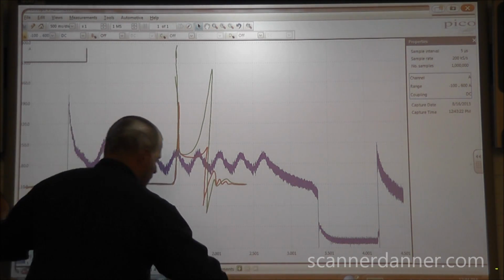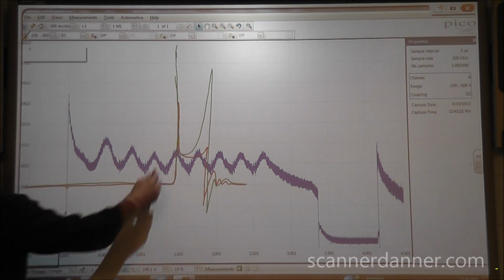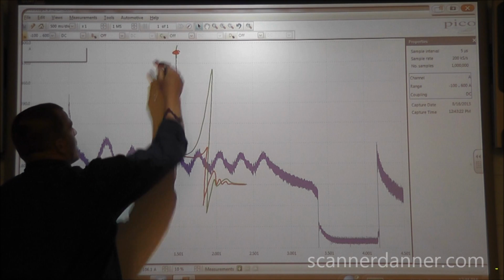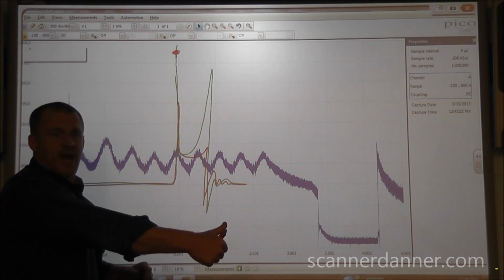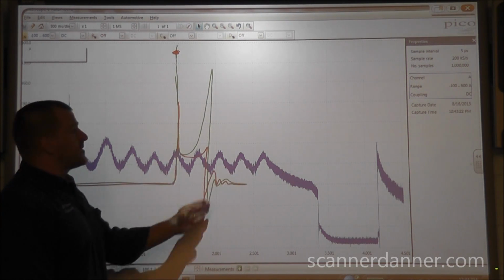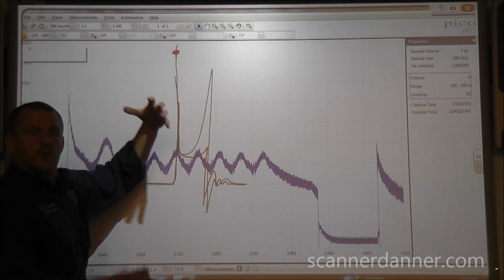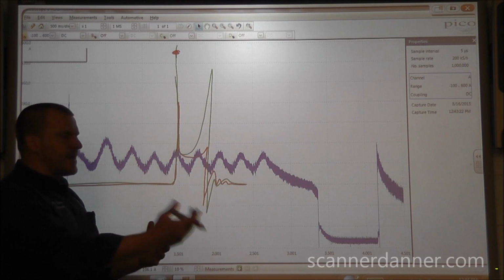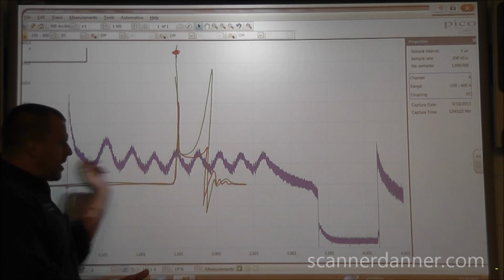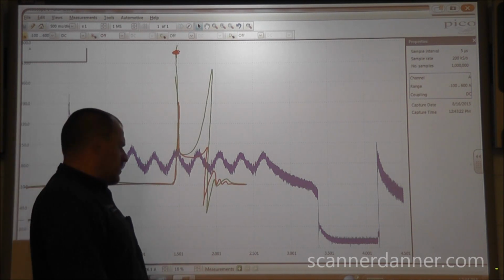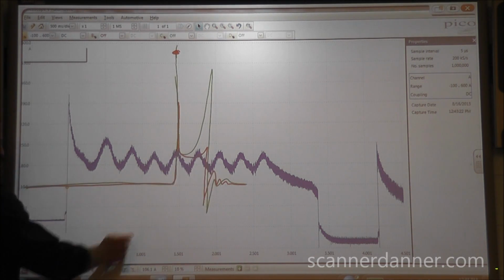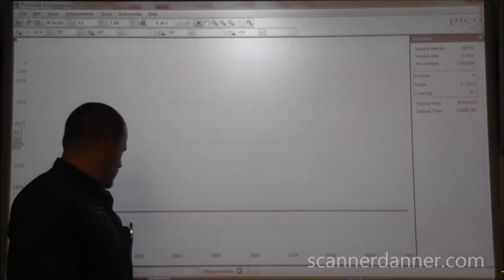What I would do is take this single and set it up here in this area. When is it going to hit that area? Only on a snap. It won't draw it at all until it hits that snap, and then it will hold that picture there. It's a way to get a really fast signal that's coming and going to stay right there on the screen for you. That'd be another time I'd use a single shot, single trigger event.